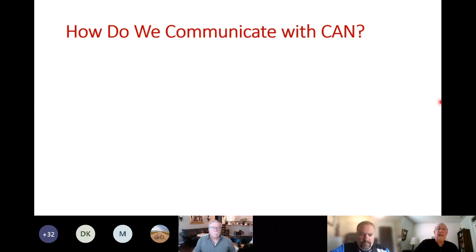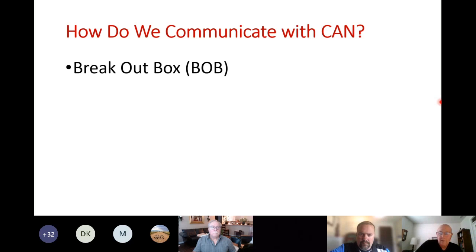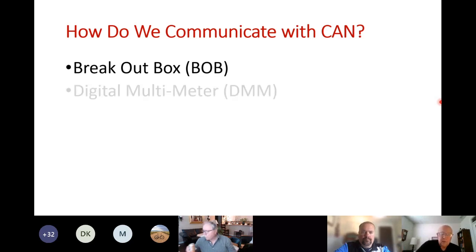And that's another thing. In other words, we have to get the students to the point where they recognize they can't use a 12-volt test light. They can look at the system to see if it's functioning, but what does it really take? Well, the first item that I'm always going to list is going to be the breakout box. And again, I'm doing that to protect the system, okay?